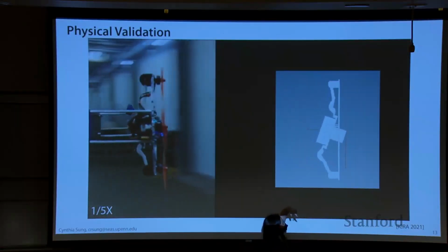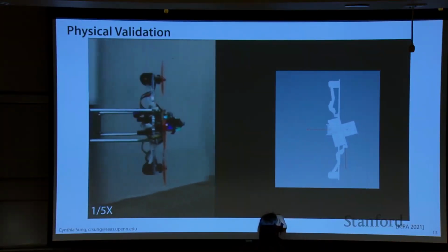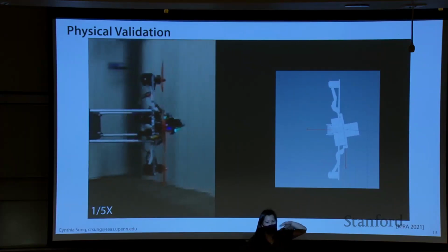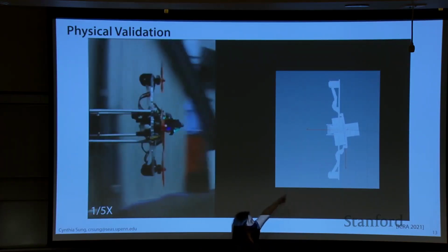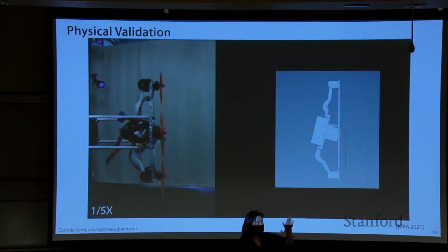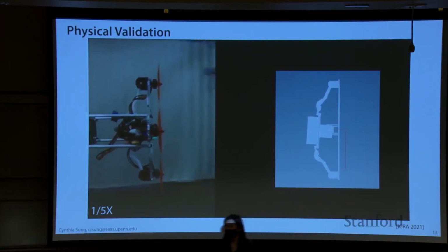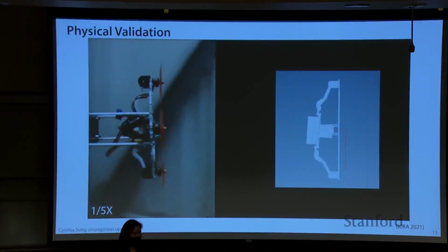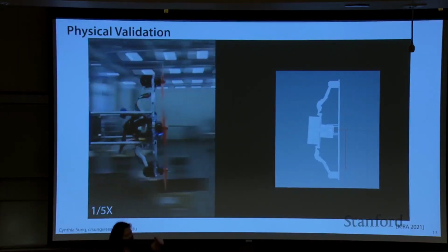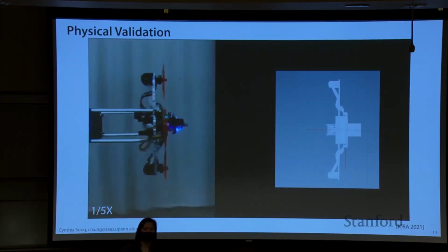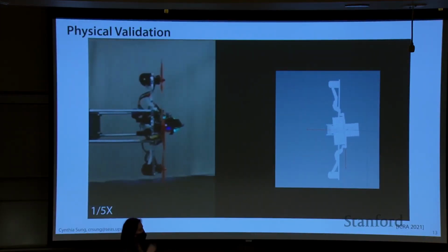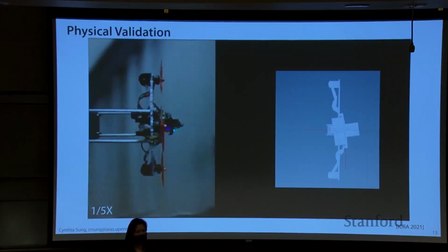The assumption that we were making when we designed the controller was that the vehicle was symmetric, right? But it's very clearly not, and there's tilting in the platform because of gravity, right? And so as a result, when the vehicle switches states, there's a huge counter torque that gets induced that causes the vehicle to go out of control, right?